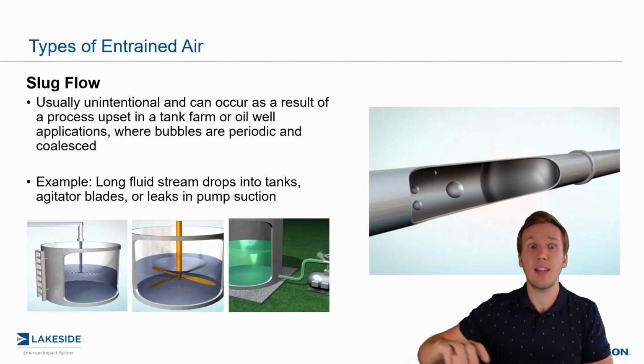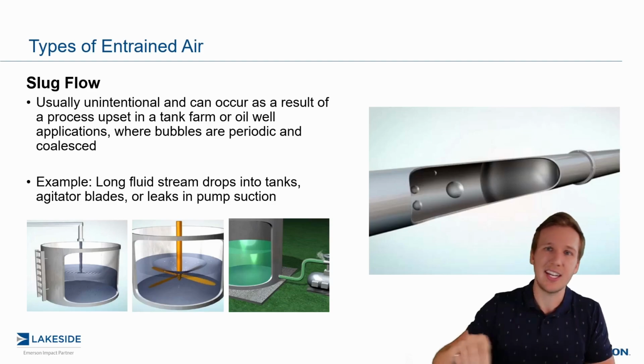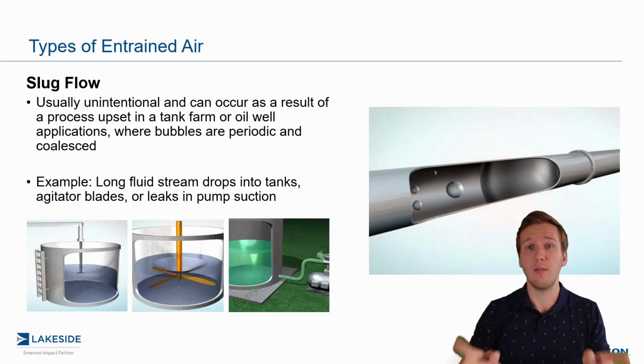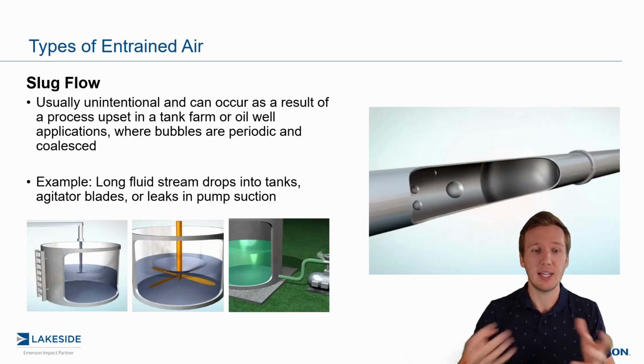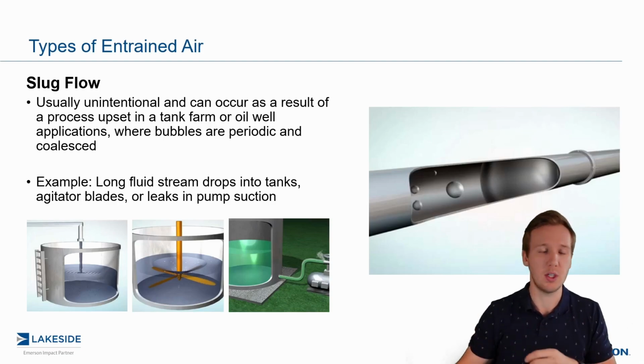Or if you have a pump that's maybe emptying tanks that are empty or near empty, that's going to suck in air. Or if you have leaky pumps as well, sucking in air, that's another way that these bubbles can get into your process. We want to avoid these where possible because these can present some challenges and are typically able to be mitigated or at least reduced.